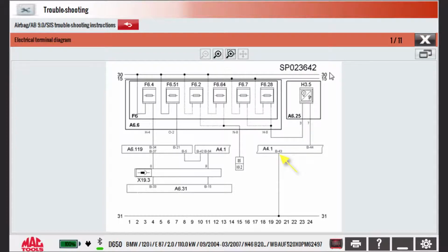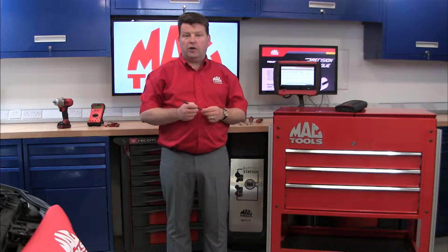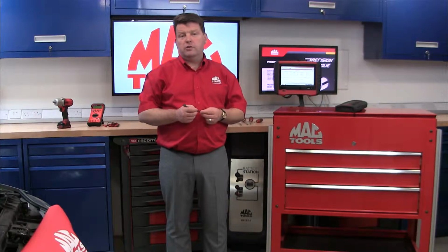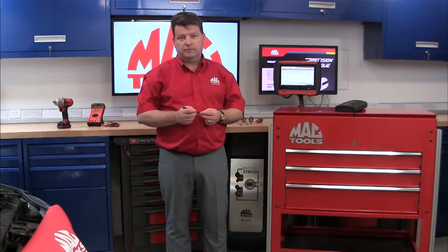The airbag control unit has an internal transistor. This acts as a switch. When the switch is closed by the control unit, the ground is applied to pin 7 of the roof controller and subsequently the lamp. Hey presto, and the lamp comes on. Now that you know how to interpret the diagram, you can start to make your own diagnostic checklists. It might go something like this.